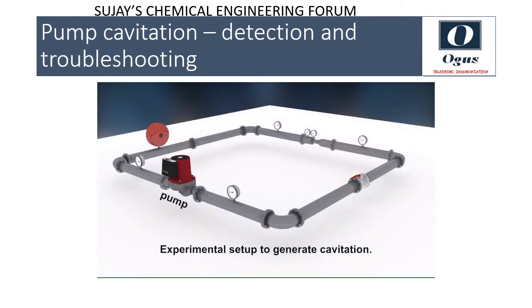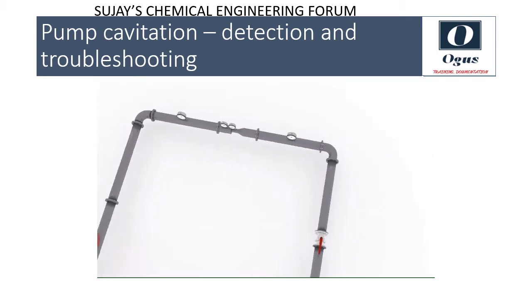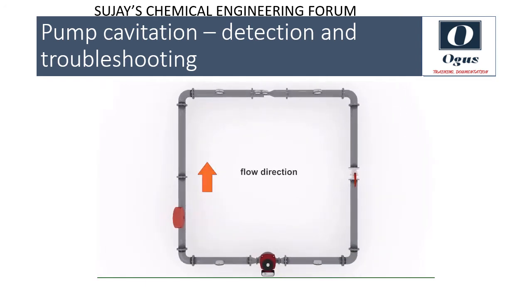When pumps circulate water through piping systems, cavitation can occur where the pressure is lowest, at the inlet of pumps and in narrow pipe sections. If the pressure at the inlet of a pump is low and approaches the vapor pressure, cavitation can occur at the pump impeller, as we have seen it at the ship propeller. The pump can deliver less water because the cavitation bubbles occupy a part of the cross-sections where the water should flow. Damage from collapsing vapor bubbles will be shown later.